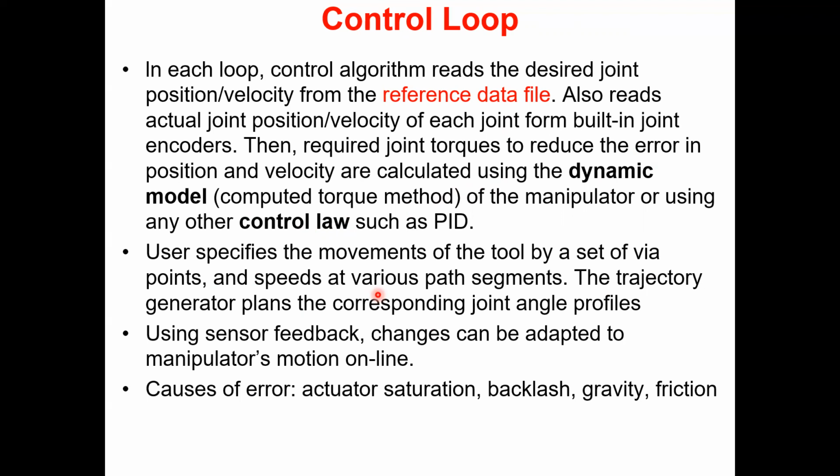Boilers are also like that. You want to maintain the pressure at a certain level. Then the water level controls maintain the level, and you are not going to change it very often. But this is a servo problem where it is bound to change. Every 10 millisecond the reference is going to change. Okay, so it is a tracking problem. It's much more serious than the regulatory problem, right? So there are a lot of errors that you can expect here.